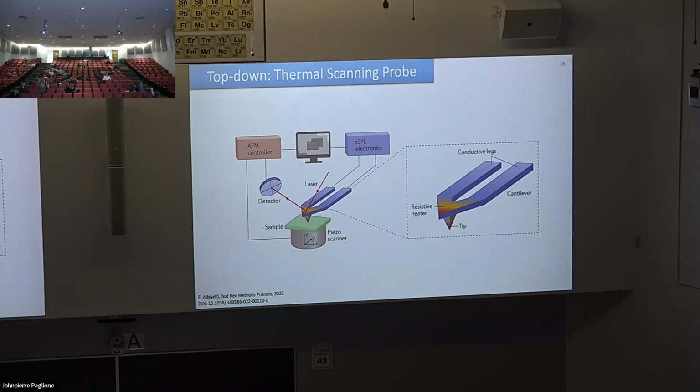And because these tips are so small, heating is extremely efficient. You can turn the heating on and off very quickly. That also gives you a feedback loop of measuring the topography and heating. So you have extremely high fidelity patterns because you immediately see what you have, and then the AFM can adjust how much it's heating, how much it's pushing down. And you can do what's called grayscale lithography. In e-beam lithography, you either have your resist or you don't. Here you can choose how much resist you have, how much you heat, and how much you push down on your surface.